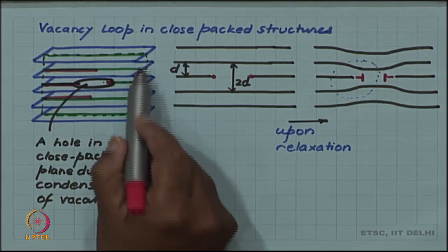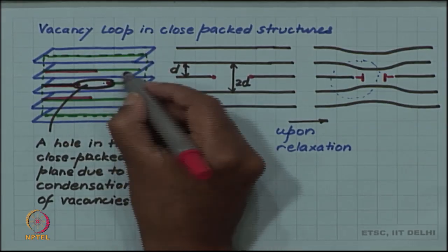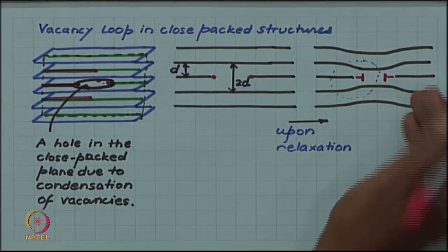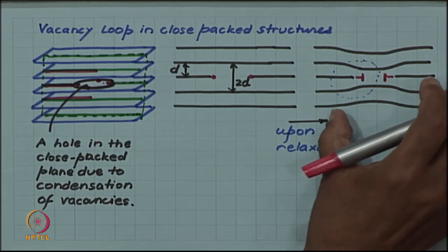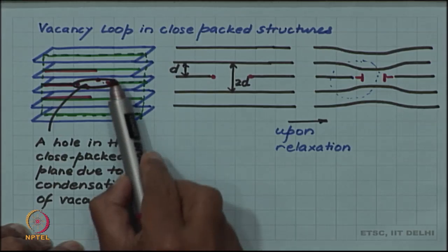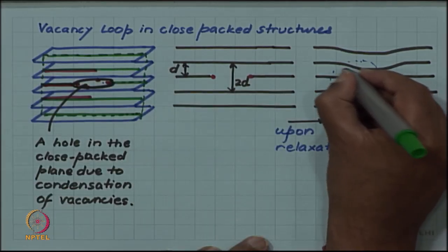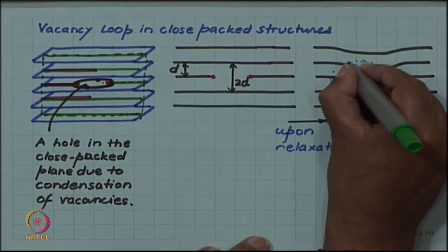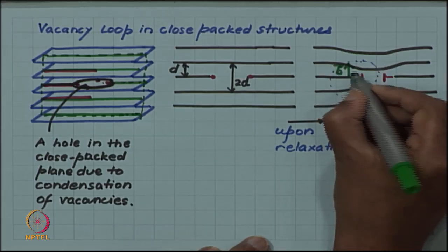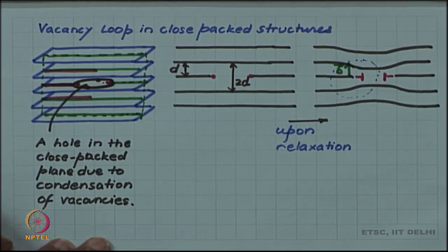but this was when we cut into this green plane. So, then we showed that these 2 points are edge dislocation lines. You can imagine that if I cut this hole through other vertical planes, all the points can be shown as the dislocation line in a similar kind of picture, because the geometry of this loop is cylindrically symmetrical about this axis. So, the entire loop is an edge dislocation, and the Burgers vector of this dislocation line, if you find, will be in this diagram vertical, because the edge dislocation line is going in at this location. So, the Burgers vector will be pointing into the plane and will be going up.